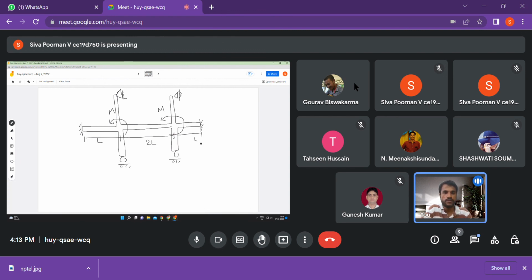So how do we solve this problem using the concept that we just saw? What is the first step? What can we take advantage of here? We can take advantage of symmetry, right? It's a symmetric structure, so we can cut it about the center and analyze only one half of it. It's making use of symmetry. We know that this point cannot move horizontally, because if it has to move horizontally, which way should it move, left or right? We cannot be biased towards any one side because it's symmetric. Therefore the only way it can move is vertically, right?